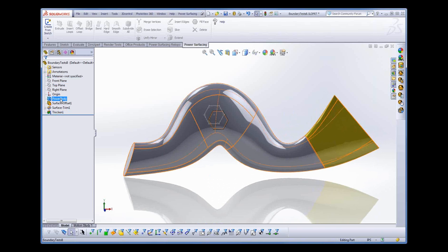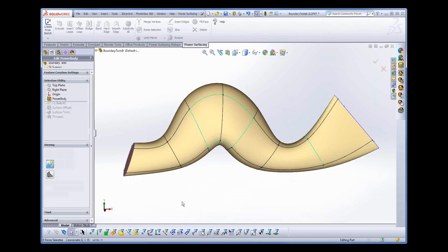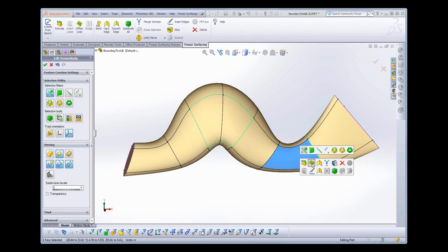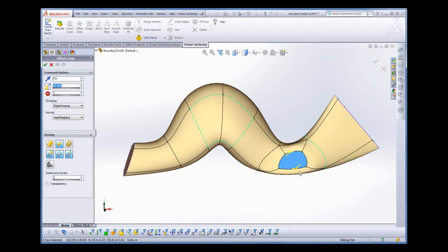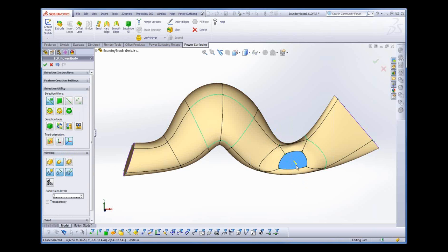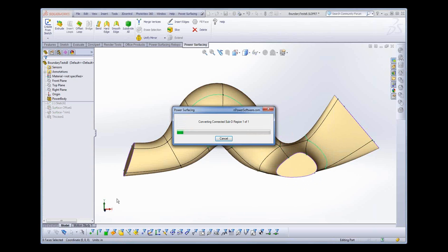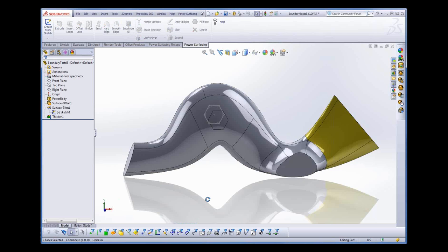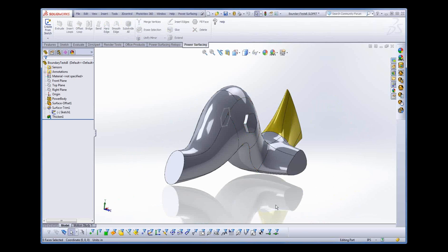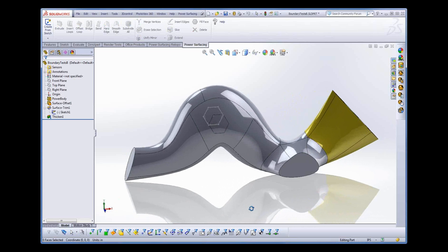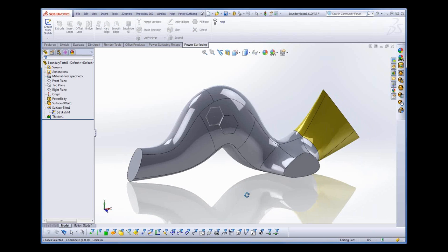And now if I go back to my power body and go into edit mode, we still have our boundary up here. But now if I go here and do that same destructive thing I did on the last one, offset, and I'll just crease it just because I like it. If I convert now, you'll see that now it's enabled us to retain the correct surface on that. So that's a really important concept to understand.